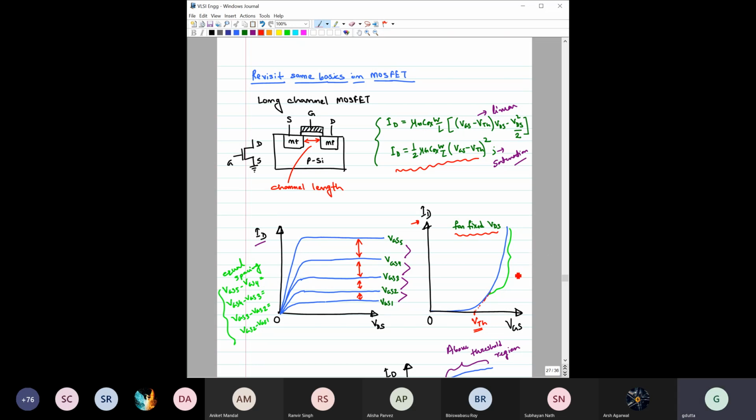Right. So you are expected to get a quadratic line here. Whenever you see a quadratic line, you have understood that this particular transistor is being operated in the saturation region. If this transistor is operated in the linear region, the characteristics would be a little bit different, because here ID is proportional to VGS, so it should be linear. If you see some region which is linear, then obviously it is in the linear region from this plot.